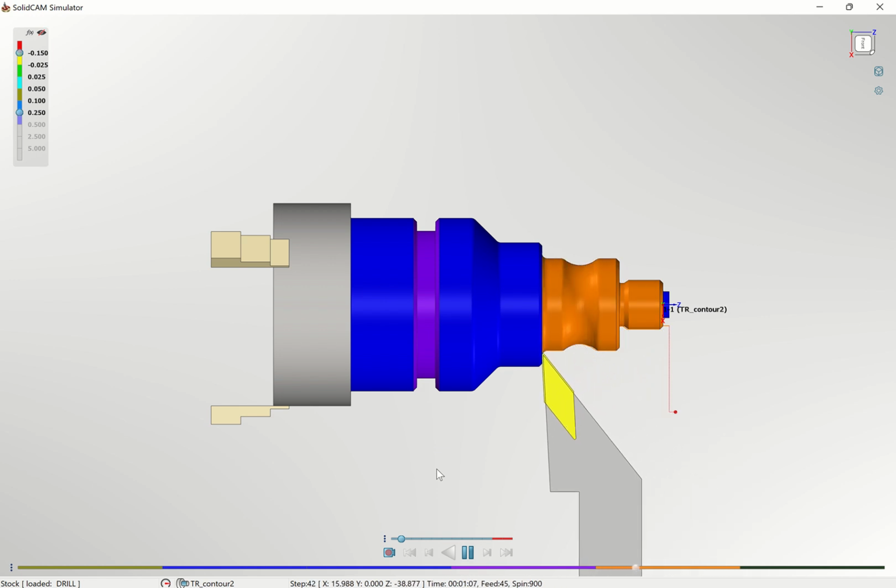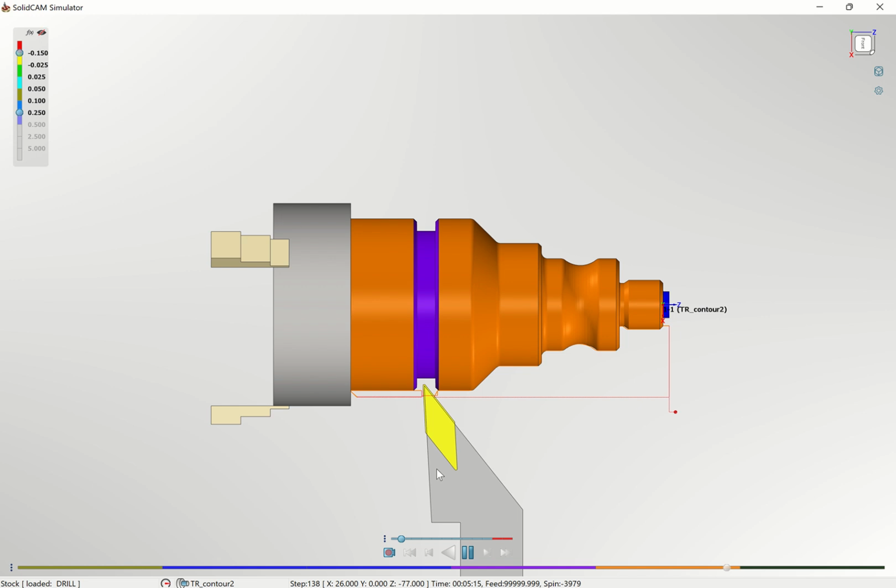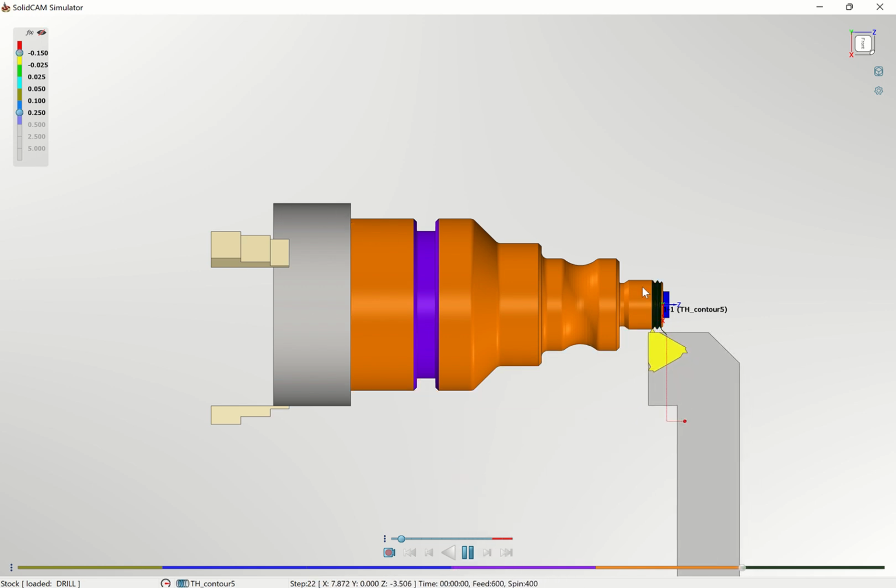Now this is the finishing operation. And remember, when you're designing your shaft, if it is a shaft to be used in a very critical area, prevent using sharp edges where the two meet. Like between this one and this one, ensure that you prevent using sharp edges.